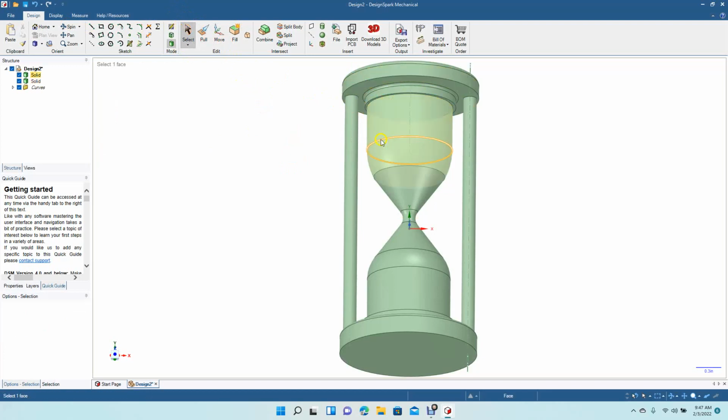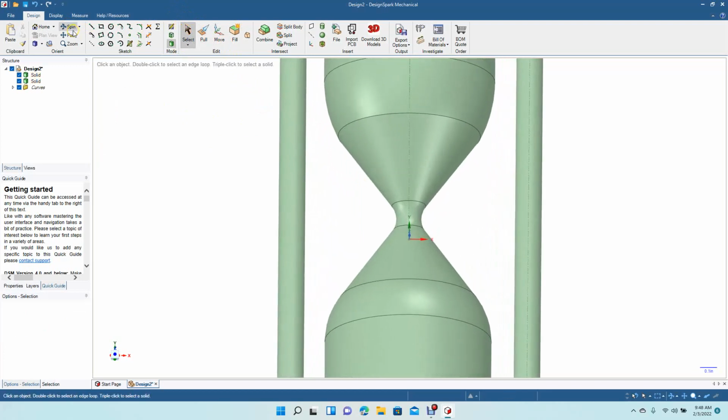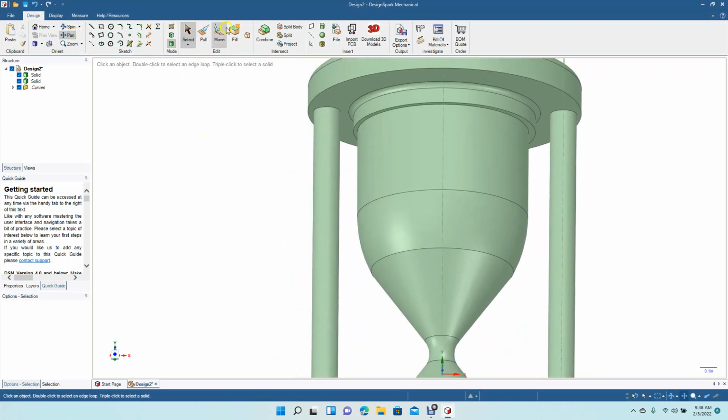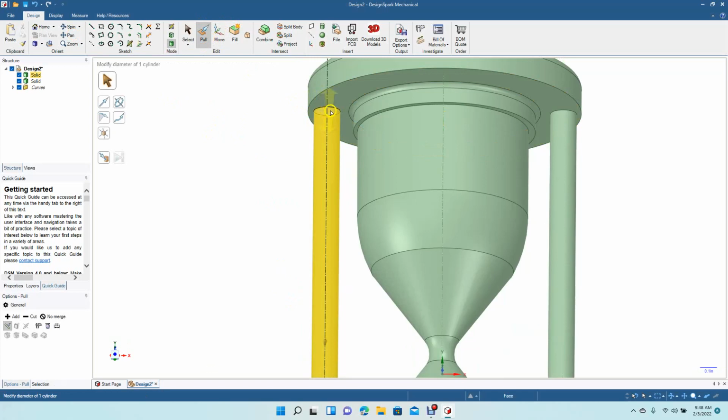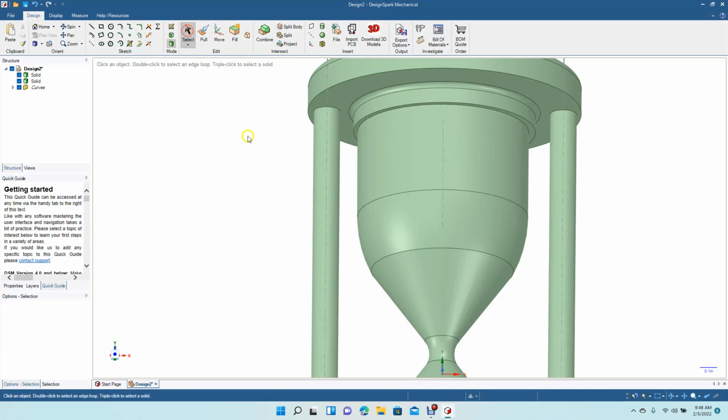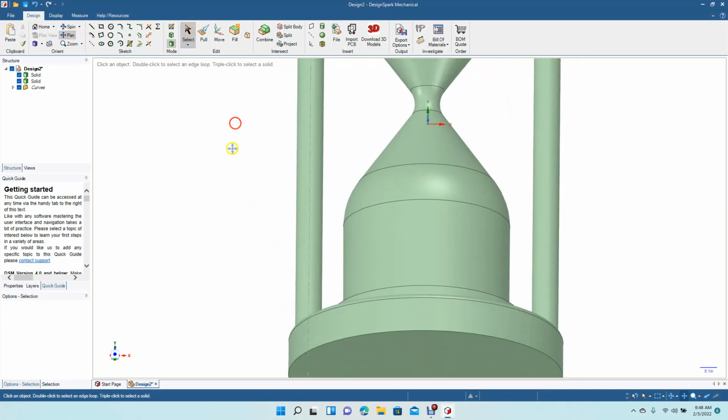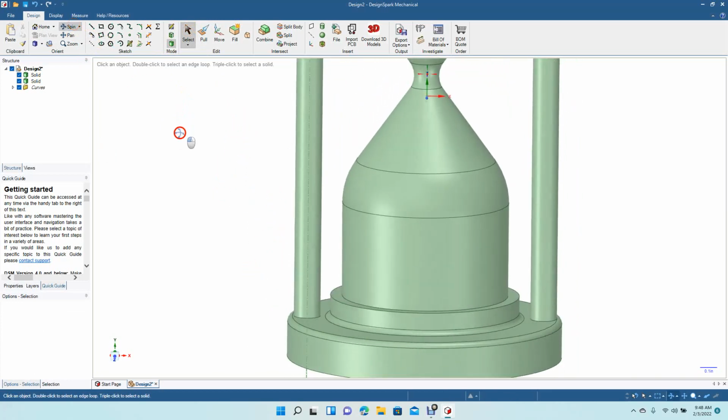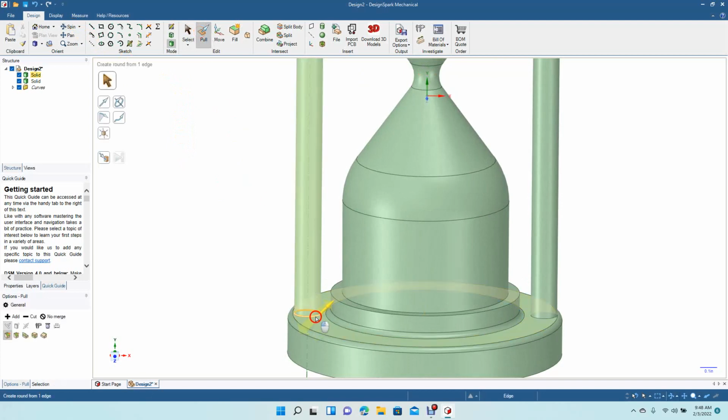I'm going to add a fillet up here. 0.03, just so these are like possible spots that could crack or break. There's not a fillet there to strengthen them. We're going to add a fillet here. Actually, we can't. All right, let's pan up. Spin. Go 0.1 right there. 0.1. Let's put a little fillet here. 0.2.